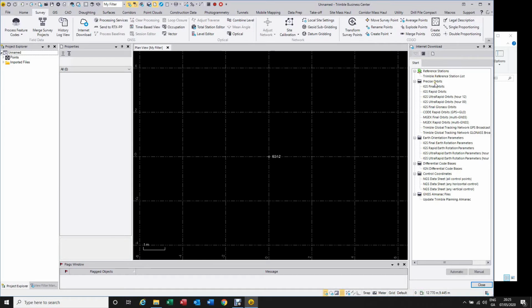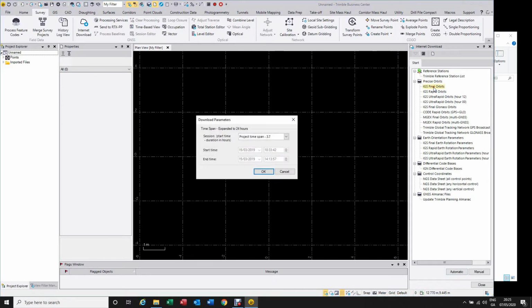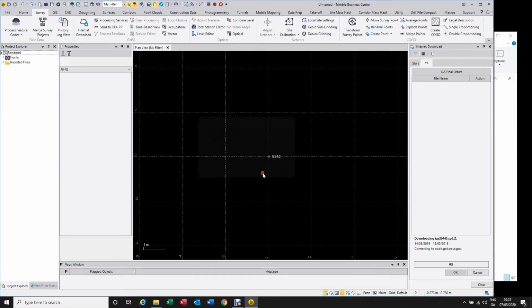First of all, the precise orbit information sometimes comes later. Even if they transmitted the orbit parameters up to the satellite and we received them via the receiver, sometimes it changes. They fine-tune this, and after a couple of days you can download a precise, final orbit.